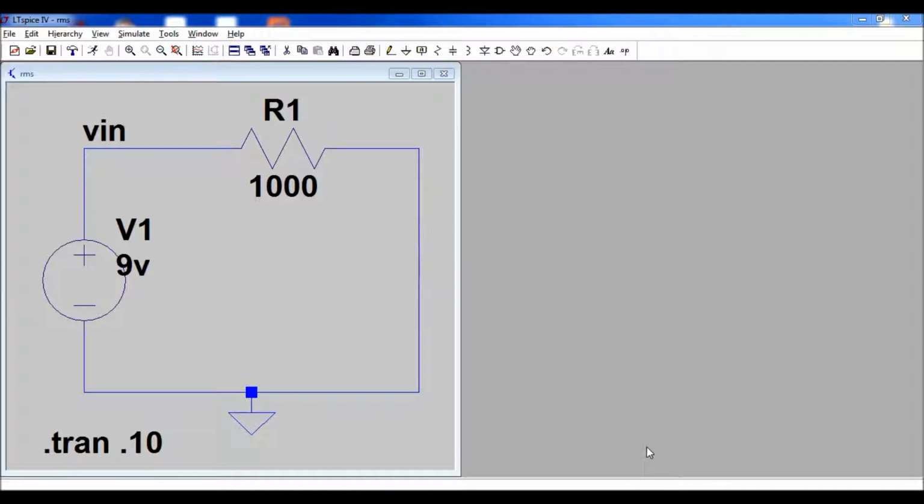So this video is about RMS. The abbreviation for RMS is root mean square. RMS value is like taking the average of a square. It is the amount of DC current applied so that the power, which is V into I, which is equal to I square R for a resistor, is the same as that of an AC signal.